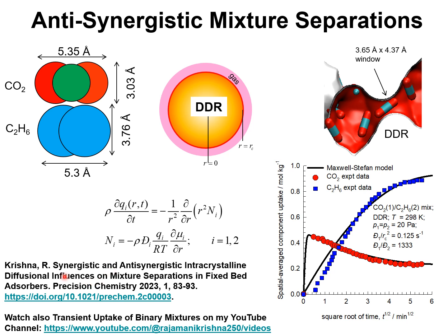Separation of mixtures of CO2 and C2H6 is relevant in the context of natural gas processing. Current technologies for CO2/C2H6 separations use extractive distillation because of azeotrope formation. In my presentation today, I'm going to discuss a different strategy for separating mixtures of CO2 from C2H6, and this strategy relies on anti-synergy between mixture adsorption and diffusion in microporous crystalline materials.